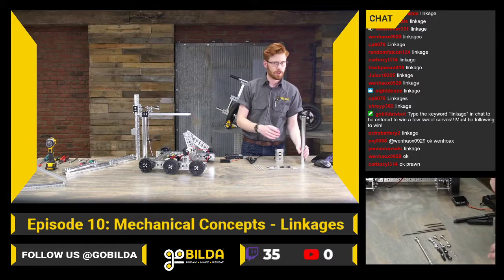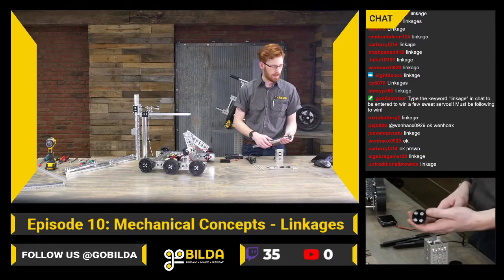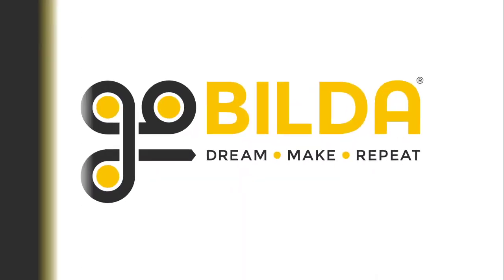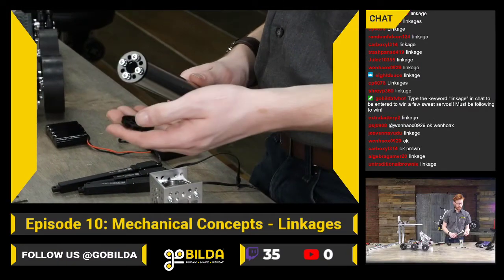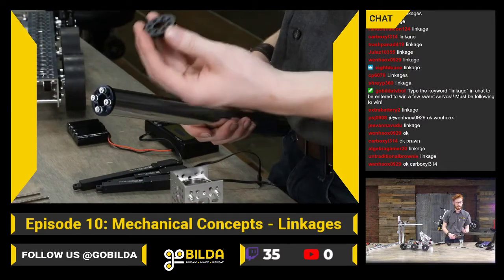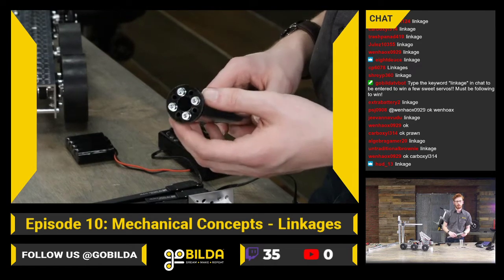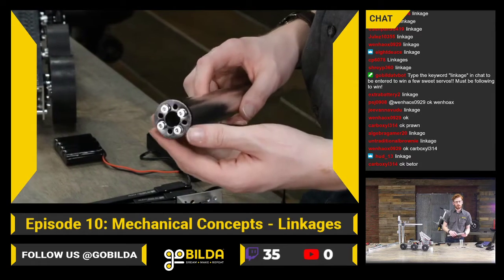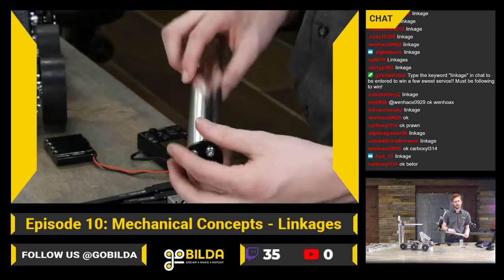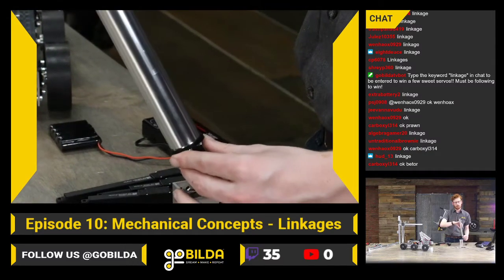Alright, so the first one that we're going to be looking at is the goTube end cap. And now this is a fairly simple part. It is basically a 36mm diameter plastic part with the goBILDA pattern in it. And its primary use case is to bolt on the end of a 32mm goTube or another 32mm surface and give a surface that is a larger OD than the goTube.